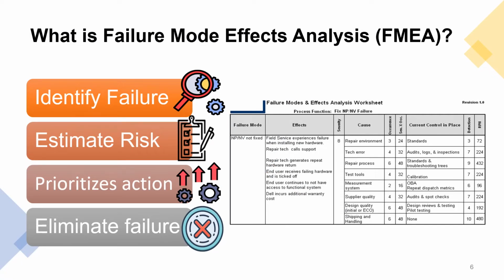FMEA is actually a systematic group of risk analysis activities from a customer's perspective, which identifies the ways a process or product can fail to meet customers' requirements or pose a threat, and estimates the risk for a specific cause with regard to these failures based on the scoring of severity. How severe is the issue to the customers?